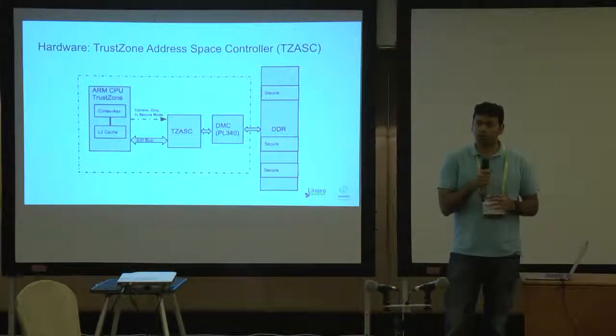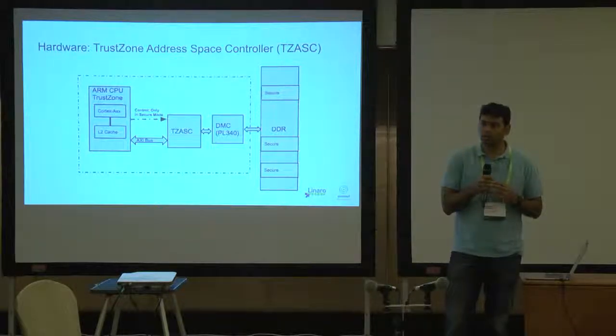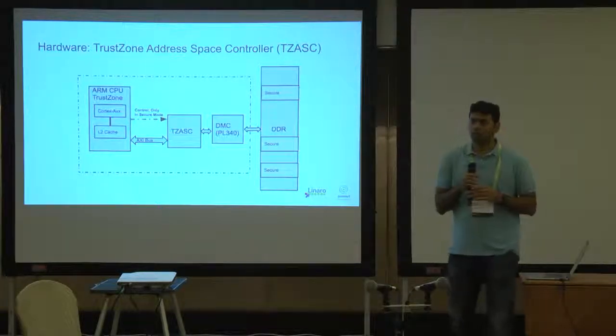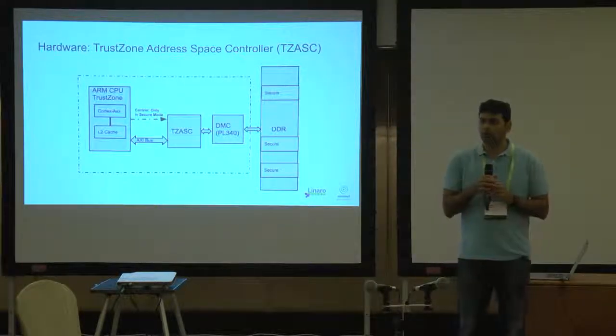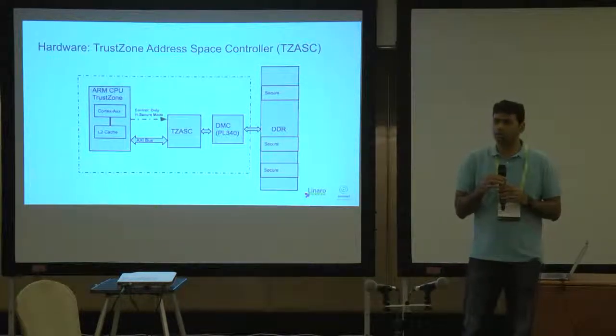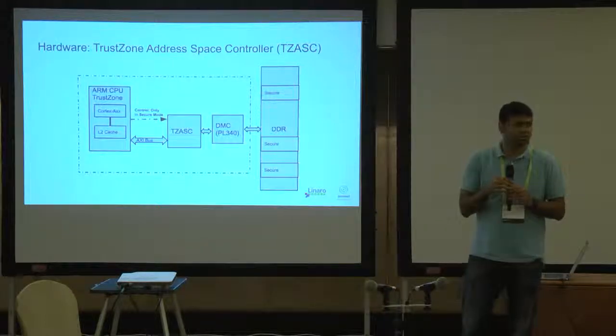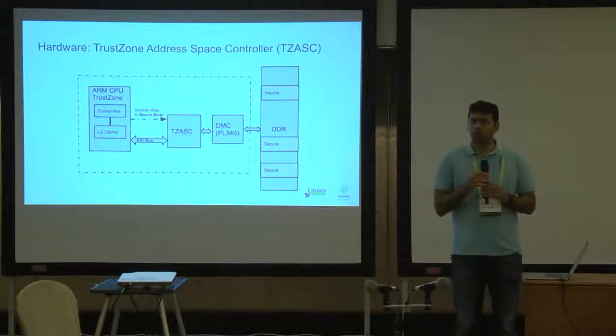But if you're using CMEM, then yeah, we use CMA, and you can reserve some CMA blocks at boot time with a little stub that we have. But you could do it in the driver too, right? From code, or you can do a carve out. Yeah. And give it a mem equals size at address and carve out some memory from Linux. Okay. And then we manage it from there. But CMEM is just one of them. It's an allocation solution. ION allocators do the same thing, right?